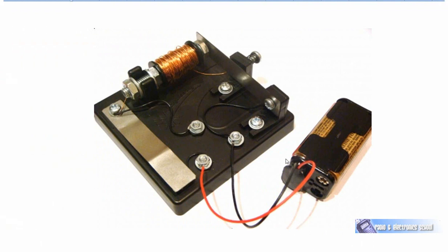While I've got this up, I'm just going to trace out the circuit again for you, because it's a rather useful model. The circuit for the electrons is from the negative terminal. We'll presume the switch is closed, so electrons are going to flow, and that is just a connecting nut, to the armature. Current flows along the armature to the adjusting spring. That spring can be adjusted in and out to change the speed at which the buzzer buzzes.